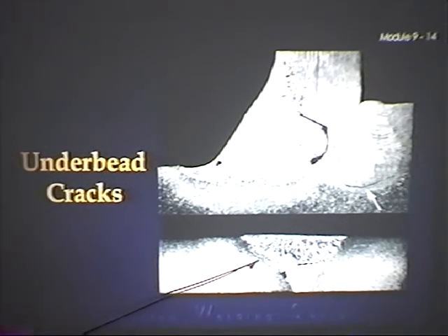And you can see the crack running outside the weld metal. So this is in the heat affected zone. This is where you have deposited the weld, but the adjoining metal, where it's a little dark out in here, this is the heat affected zone where the metal structure was changed by the heat of welding, but it didn't melt. You got it hot enough to change the structure, but not hot enough to melt it. That's the heat affected zone. And you can see that it's pulled and cracked right along in the heat affected zone.